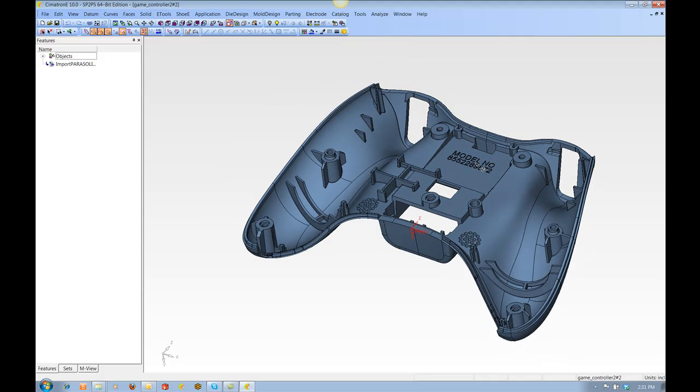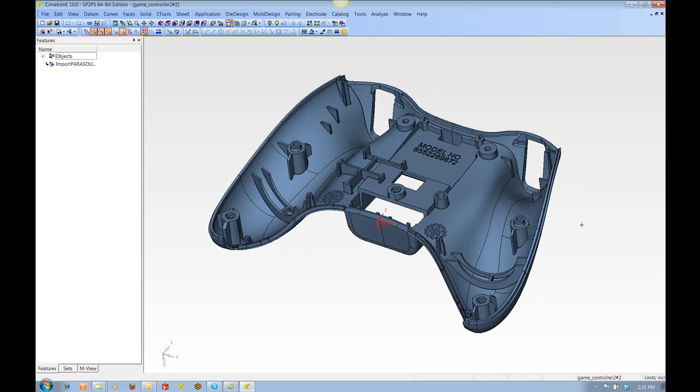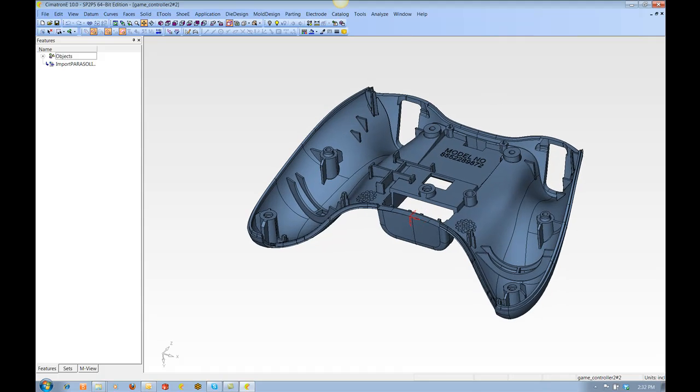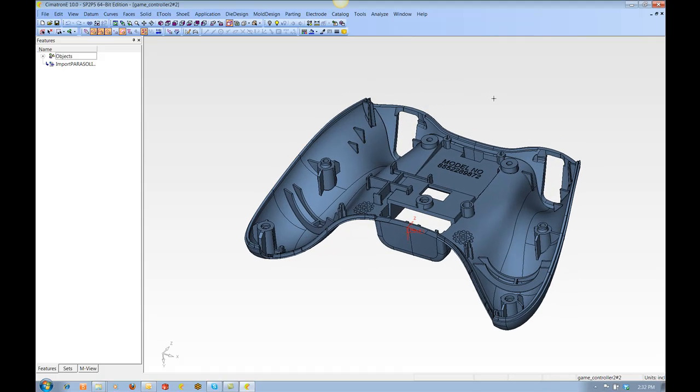Now there's not much more that I would do with this file because this is our master file. We don't want to start splitting surfaces and creating runoff or doing any kind of work in this file. This file needs to stay our master file in case we get an engineering change from the customer. We want to be able to compare something against it. Plus we call it our cover-our-ass file, right? This is the data the customer gave us. But I would do one thing in this file, and that's create a coordinate system that'll be a little more useful at the next step.